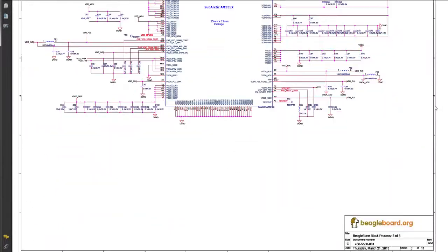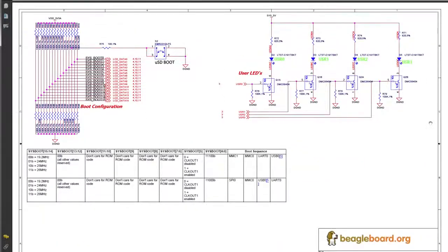So you can see if you go down, for example, here's a set of pins, sysboot 0. These are LCD data 0 through to 15, and you can see that there's already external resistors on both sides of the pins. So it's important that you're aware what's actually happening in the hardware, not inside the microcontroller, but outside on the circuit board.